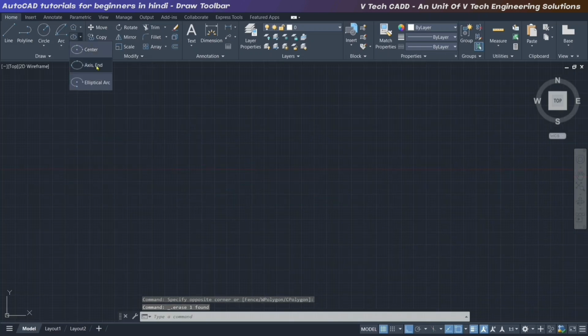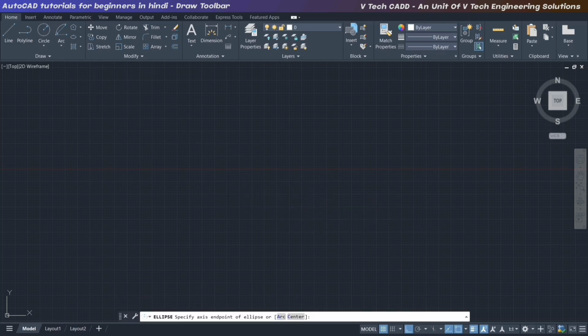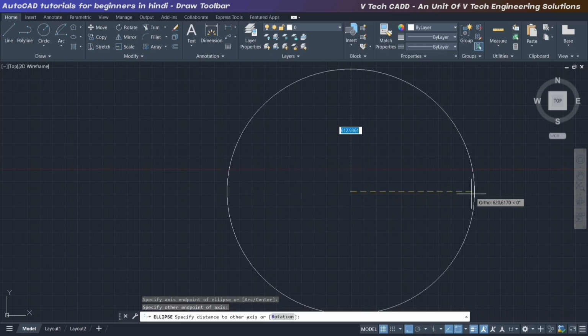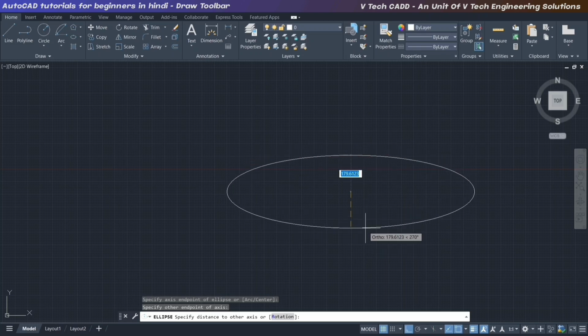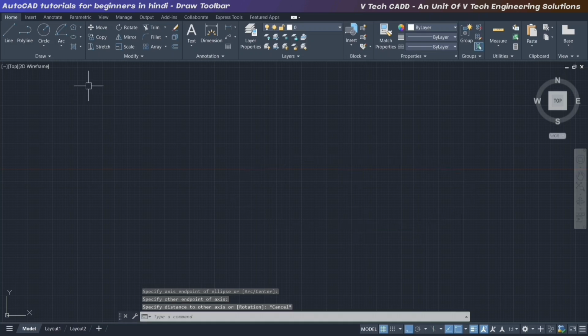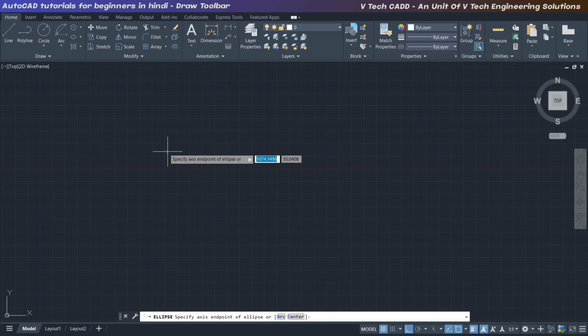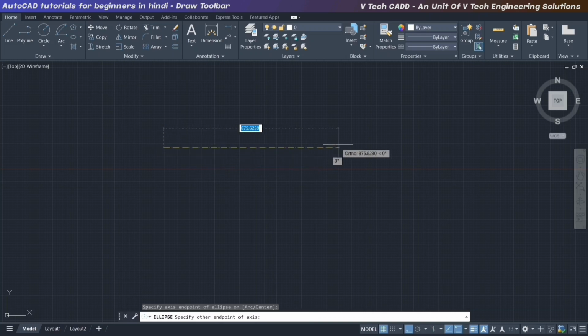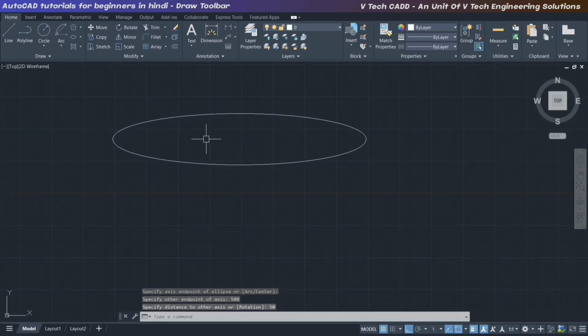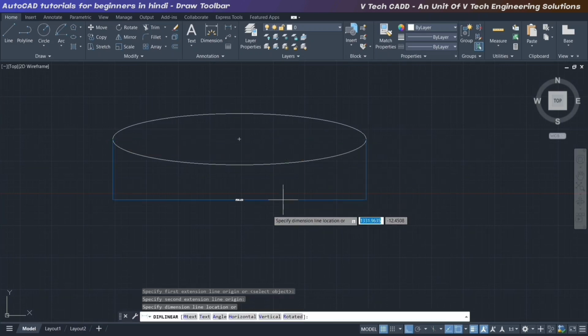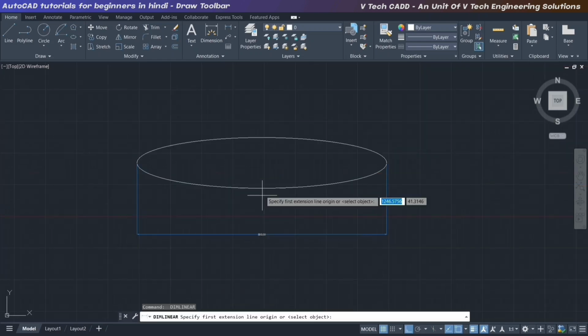Okay, and axis and end. You need to make the start and end point here, and the height. This is free form. In the first command we took the center and end, and here we have the option to draw by start and end using an axis also. Take the value of 500 mm. This will be a complete 500 mm, and put the value of 50 mm for height. You can check, this will be 500 mm. Okay, and height will be 100 mm.